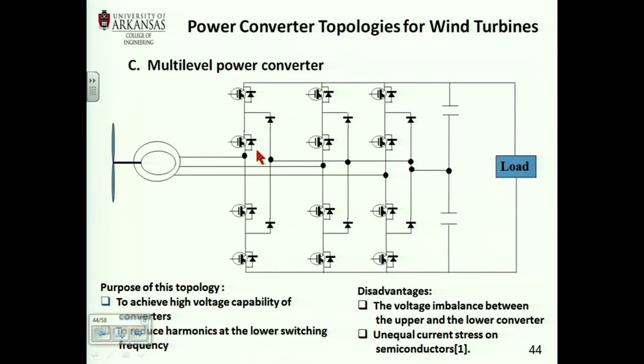So that's the reason why lower voltage devices are more efficient. They have less energy losses than a high voltage device. A typical case is, for example, 6,500 volt IGBTs. If you look at the switching losses, they are very lossy devices.